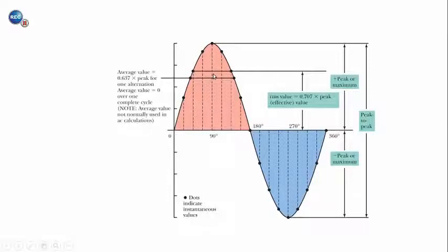And so if we were to do that, the value that we get is going to be equal to 0.707 times the peak value. And again, we can prove that with calculus. We won't bother doing that. We just want to make sure that we remember this formula. The peak value, if we multiply it by 0.707, we get what is called the RMS value. Now the RMS value is important because it is the equivalent AC voltage to a DC voltage that has the same power dissipation value.